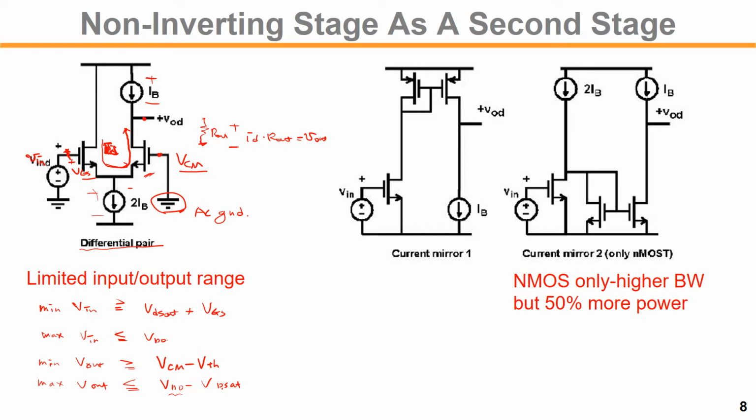To increase the input and output range, we eliminate the tail current source, so that we can have just a current mirror structure like this. We have input coming in, the input goes up, the current flows, and this current is mirrored onto the output. Through any equivalent output resistance there, the current flows through the resistance. It shows a positive voltage gain, right?